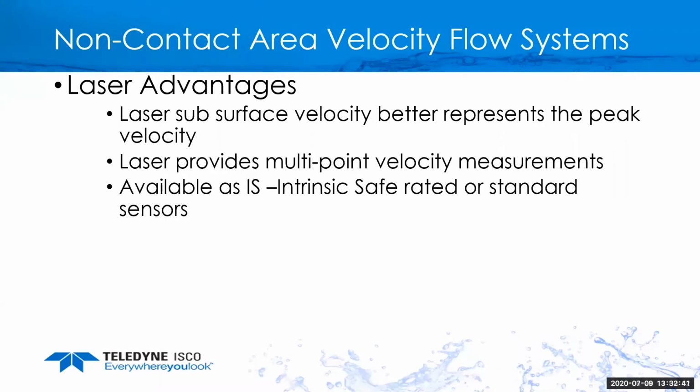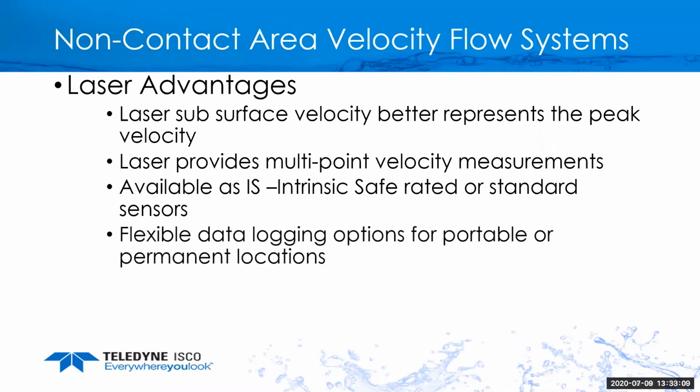Darrell mentioned that every manhole technically is classified Class 1, Div 1, not Div 2. And so you have to determine, what is your risk assessment on that? Do you have to follow that? And more and more we're seeing that people are following that Class 1, Div 1 rule because it doesn't cost a whole lot more for the meter itself. The performance is not degraded because of that. And so you're playing it safe the whole way.